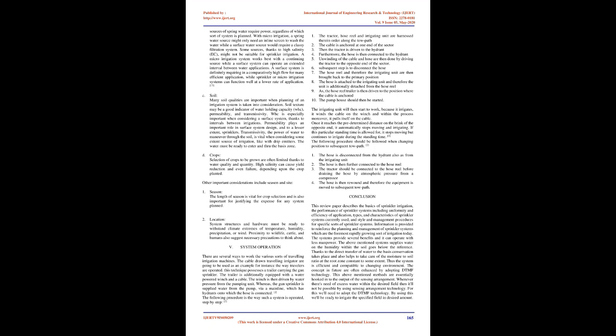Fig. 5. Different methods and their features. 3. Some rules for system design. 1. Mainline should be downhill. 2. Lateral should be laid across the slope or nearly on the contour. 3, 4, 5, 6. For multiple lateral operation, lateral pipe sizes shouldn't be too different in diameter.